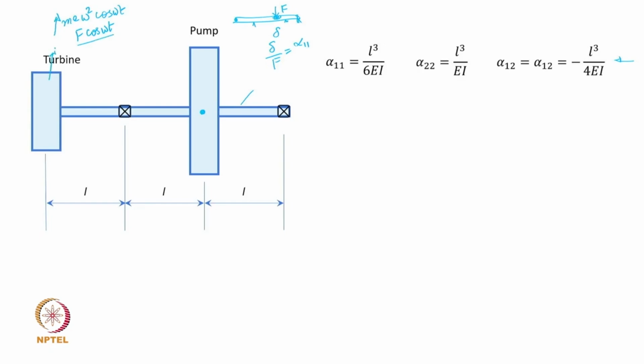You can as well consider the unbalanced excitation or any harmonic excitation at the other mass, but that is going to be quite similar to what we have seen in the multi-mass or 2 degree of freedom 2 mass system, where the response due to one excitation you can add up algebraically to the excitation from the other mass by appropriately accounting for the phase between the two, if there is a phase, and obviously there will be a phase difference of the excitation function here. Both excitations cannot always be in the same phase.